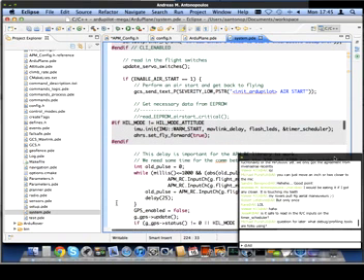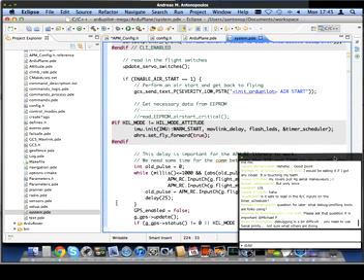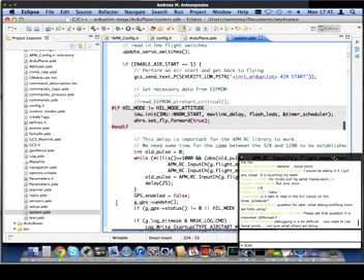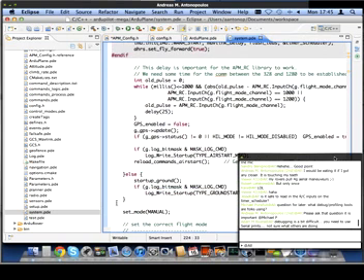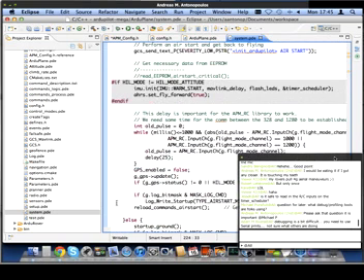Finally, we check for the possibility of air start. ArduPlane, unlike ArduCopter, can support the possibility of the board rebooting in flight. We're hoping that will be an extremely rare occurrence. Basically, it'd be something like a brownout, and in theory, it'll be able to recover and get its leveling parameters, barometer base pressure, the ground pressure, ground temperature, out of EEPROM, and continue flying. I'm not sure how many people have actually tested that by deliberately rebooting an ArduPlane in flight, but the code is there to support it, at least in theory.